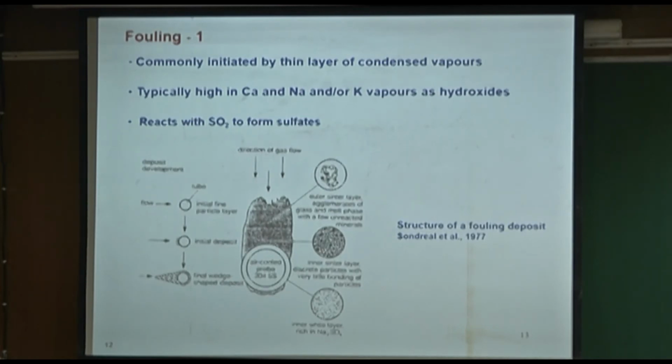So often there are ways in power stations with a high amount of pyritic sulfur to actually remove the pyrites during the coal preparation stage, because that is a very, very problematic one. Otherwise you have only organic sulfur, not a problem. It will go out as sulfur dioxide, and then you can capture it using the desulfurization unit downstream from the flue gas. And if you are careful enough, you can get some good sulfur to sell as well.